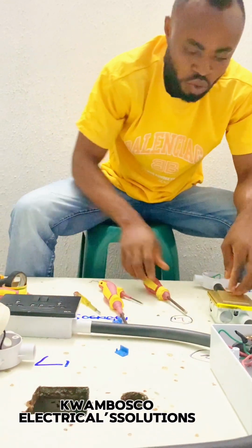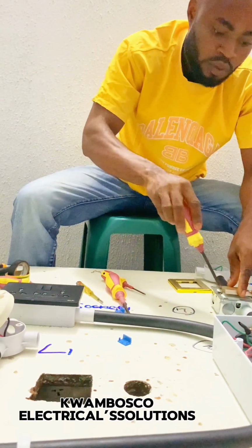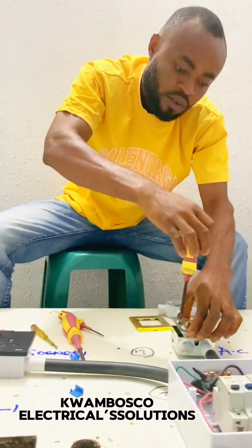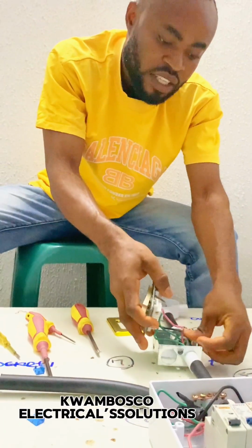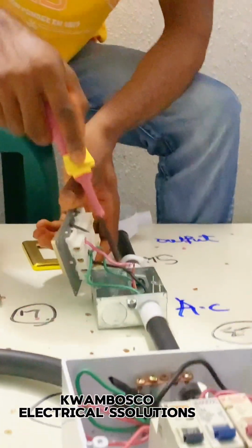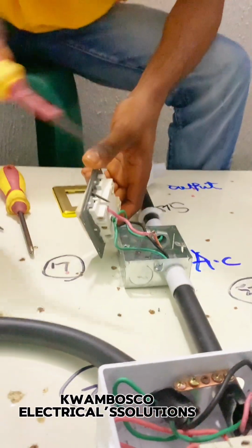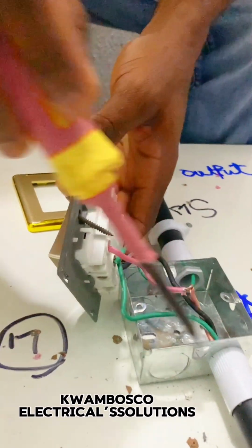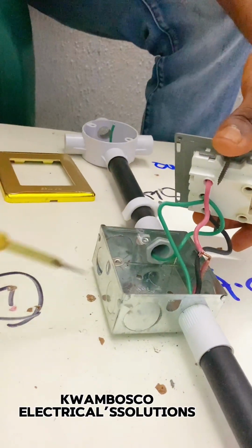So what do we do? You open your socket, remember it is off, you open the socket or switch anywhere the fault may be coming from, your socket or AC or water heater switch. Okay, the earthing cable is leaking here. Now look at the live wire, the live wire is naked. The live wire is naked and it was in contact with this knockout box. And remember, this knockout box is metallic, and we all know metal is a good conductor. So that's why it's bringing out light.